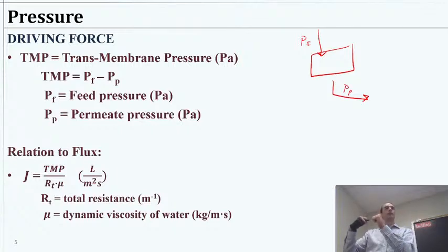Now, if you're really squeezing on it and the membrane itself is letting a fair amount of water through, you could squirt water. It would have some pressure based on the pressure you're applying, but it will have dropped compared to if there was no membrane there at all, right? It would act like a squirt gun, or a pool toy that shoots water out, except that the filter is dropping that pressure. So across that membrane, we have a pressure drop that's expected. So anytime we have a flow, we expect that there will be a pressure differential that is driving the water. So it's really that difference that is the force we can use to push water through.